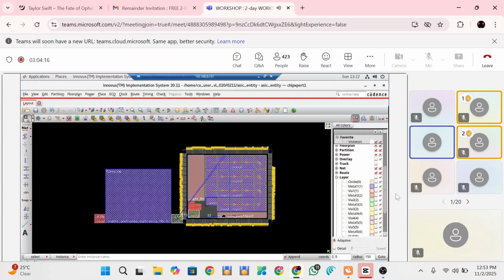Like, what we do is use different designs and check which one is best suited for that design, like a trial and error. For power, you're talking? No, for power there should be no trial and error. Standard values are to be given by the power engineer or the principal engineer. They have to use the grids or the stripes according to the spacing between every metal layer, which will be given by the principal engineer.